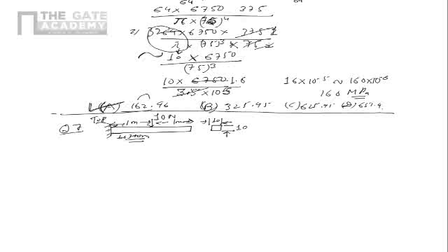Bending stress sigma is equal to the moment, which is 10 by 1, upon I, which is 1 upon 12 into 0.01 to power 4, into 0.01 by 2. This is the value of bending stress in this beam. So the maximum bending stress will be 12 into 10 into 0.01 by 0.01 to power 4 into 2.